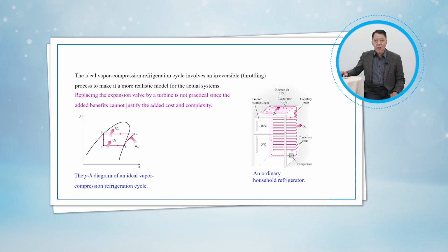Another diagram often used in the analysis of vapor compression refrigeration cycles is the Ph diagram, as shown in figure 12.12. On this diagram, 3 of the 4 processes appear as straight lines, and the heat transfer in the condenser and the evaporator is proportional to the lengths of the corresponding process curves.